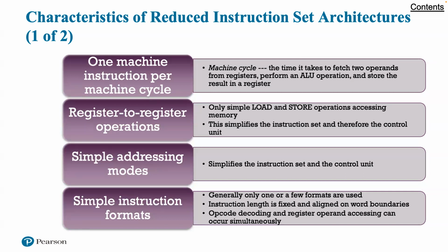With simple one-cycle instructions, there is little or no need for microcode. The machine instructions can be hardwired. Such instructions should execute faster than comparable machine instructions on other machines because it is not necessary to access a microprogram control store during instruction execution.